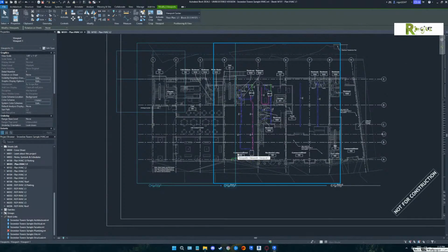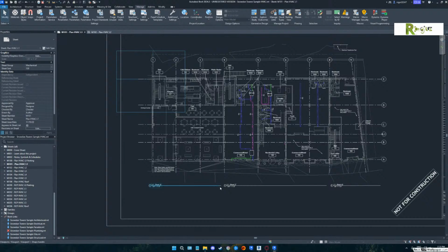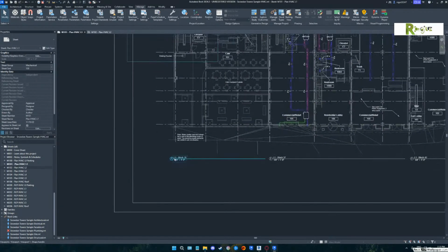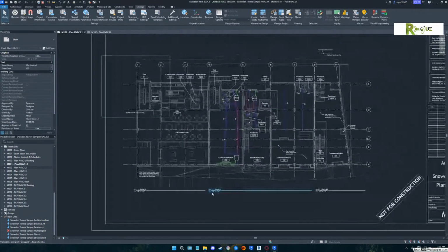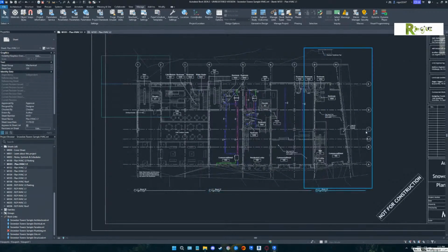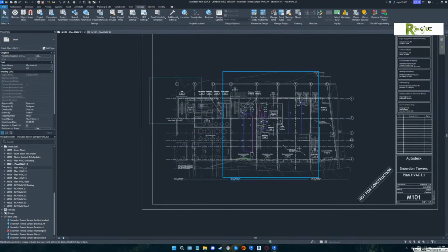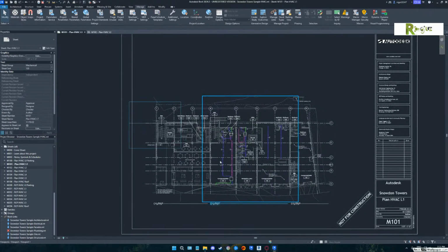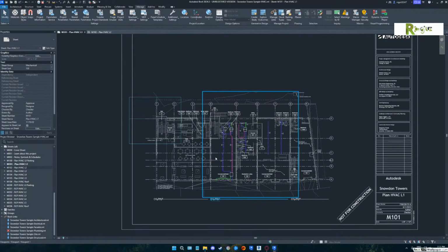That's why your levels are off, because they have 3 different level 1s. You see how they have L1, block 35, block 37, block 43? If you looked at a section going across the building, it would make more sense to you. They don't have any sections right across there. Draw one in. Go to your second level and draw it in.